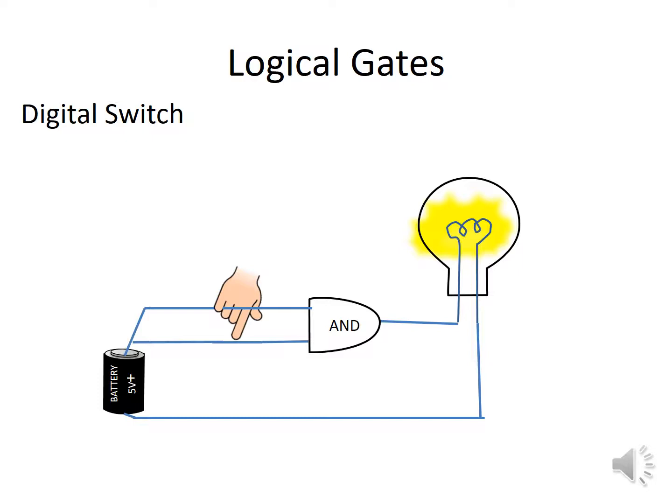And now you can see both are in, and the AND gate is saying, fair enough, I will turn my output on. So that's a logic gate. It's a bit of circuitry, and an AND gate says when both my first and second inputs are switched on, my output will be on. And that's where the word AND is used in it. Okay.